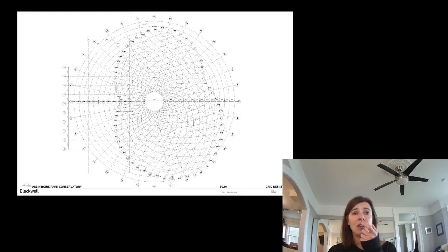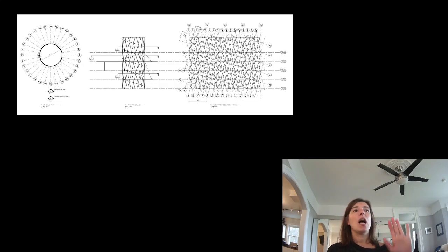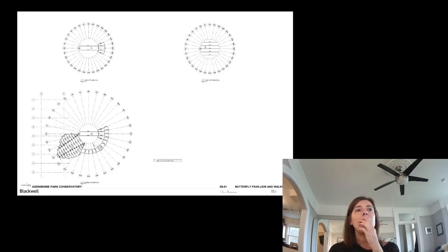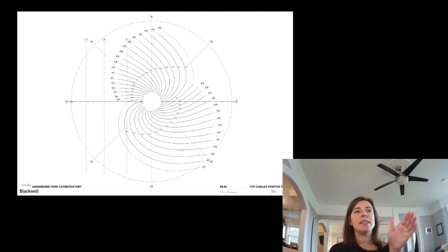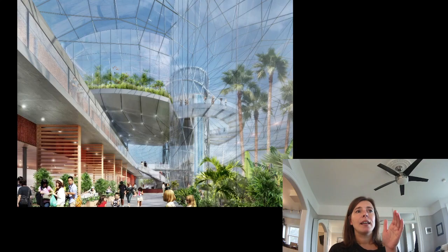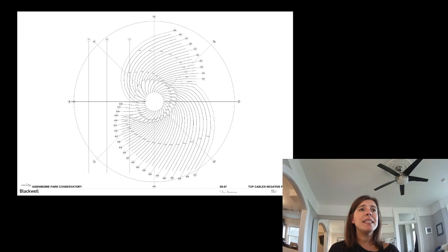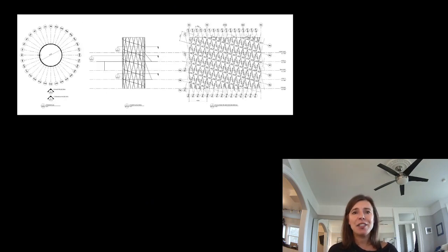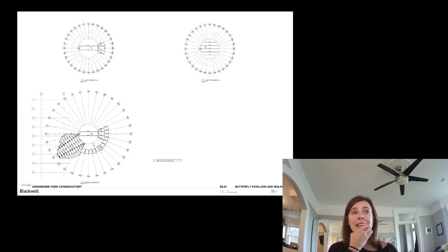One of the ways they handled it was to send a 2D diagram, an unrolled elevation for some of the objects, showing different grid lines. The best part is they actually sent a list of geometric node points. So they actually sent files with X, Y, and Z coordinates for all of these points to be able to say to the contractor, this is where they are, this is where they need to be.